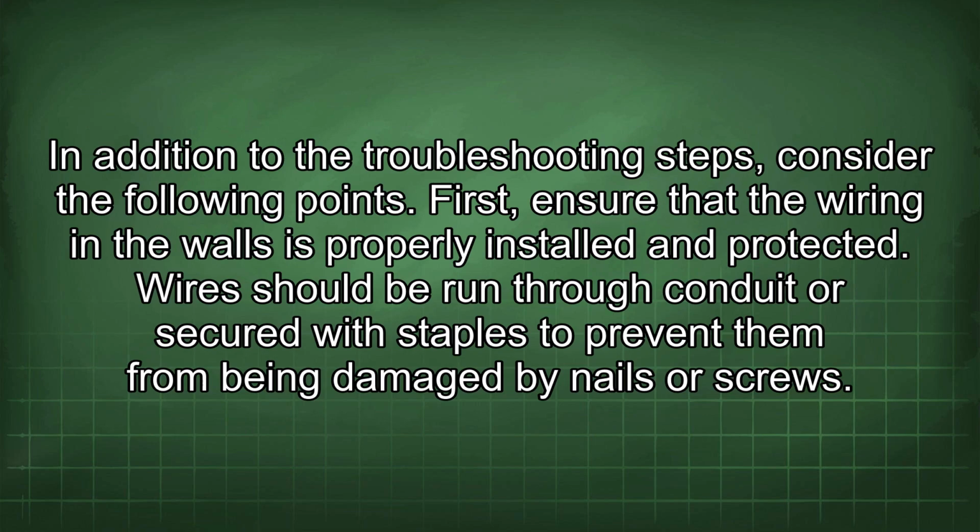In addition to the troubleshooting steps, consider the following points. First, ensure that the wiring in the walls is properly installed and protected. Wires should be run through conduit or secured with staples to prevent them from being damaged by nails or screws.